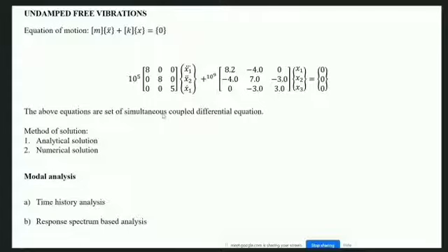So there are two types of solution. One is analytical solution, and the other is numerical solution. And the very accurate analysis which we can carry out is called the modal analysis. That means, as I have discussed, that the basic consideration is that at any instant of time, the displacement vector is a combination of the independent mode shapes into a time function which is acting as a weighting function for that mode shape. And with time,